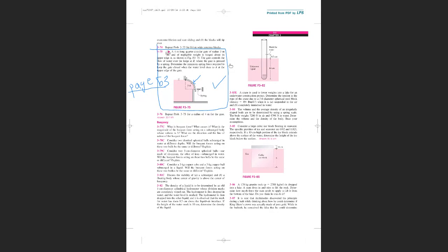The issue here is there is a spring force. So in order to get the forces on the curved surface, you will assume there is no spring. And then, after you get the forces on the curved surface, you bring in the spring into action and you get the force on the spring. Okay, so that is hydrostatic forces on plane and curved surfaces.